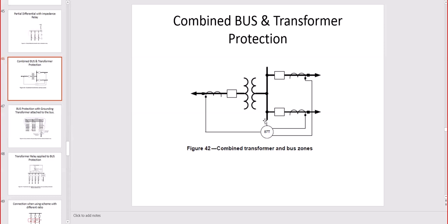And yes, you can include the bus sections, the portion of the bus that is connected to the transformer, into the 87T. Implementation typically can be with Schweitzer 487E, or also the GE T60 transformer protection, which we have in our Unit 6 and Unit 3.